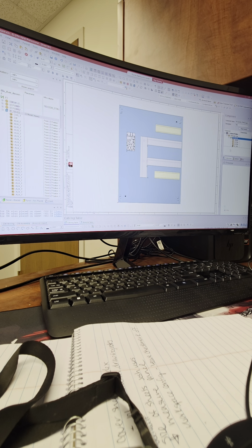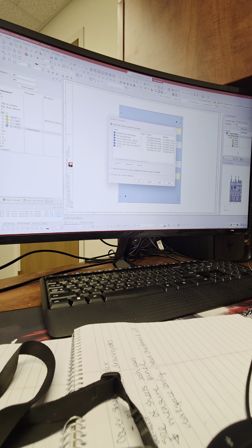Usually, if you do this on the whole project level, instead of doing this over the device, which would have been enough for what you just did, but if you do it on a folder level, like the solid state relay folder level, one level up from where you currently selected, if you do update all components in project here, it's going to flag every single item that was ever edited between you starting this project and you messing with the library on some level.